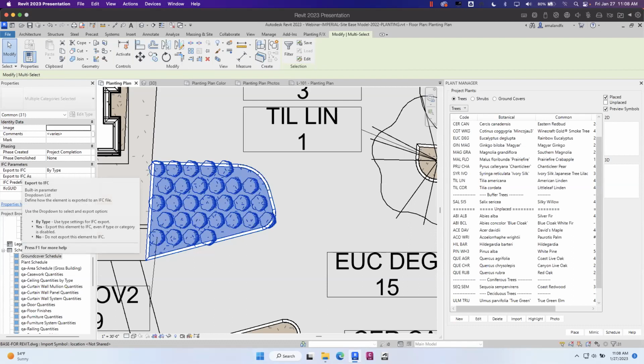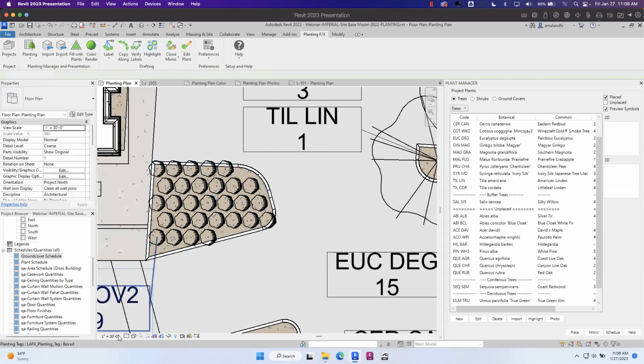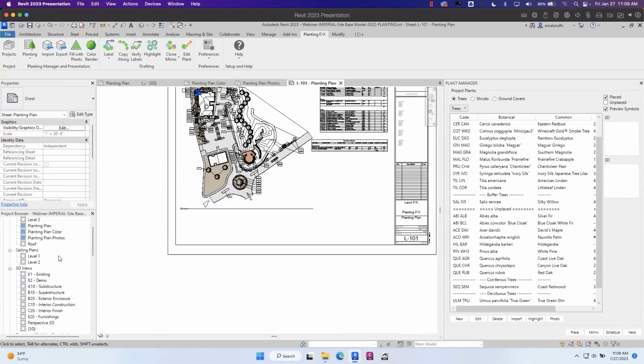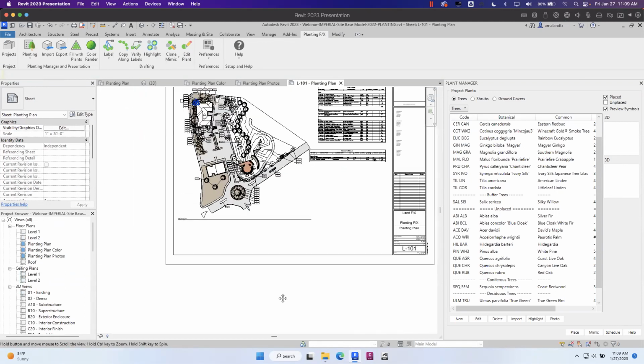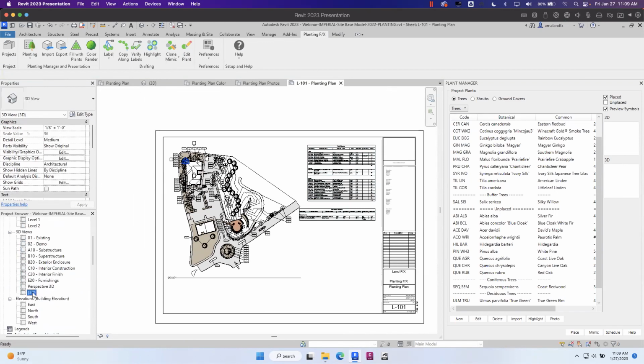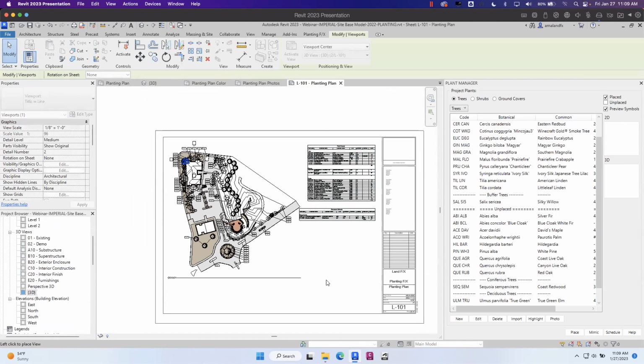Mark asks, I would assume, can you combine 2D and 3D views in one layout sheet? Yeah, you should be able to. It's a very much more intuitive way of placing viewports. The way that I placed this viewport is I just grabbed this view and dragged it over, like I dragged over the schedule. So it's really just as easy as grabbing your 3D view and dragging that one over. Oh, it's probably huge.